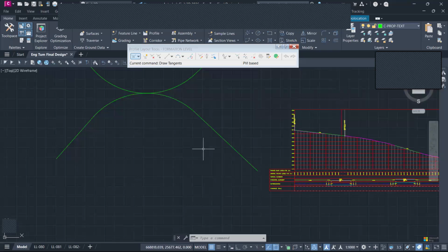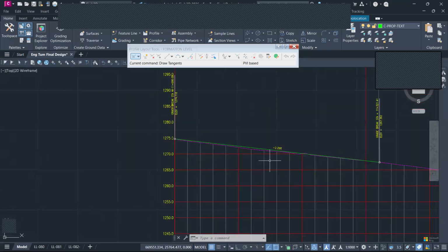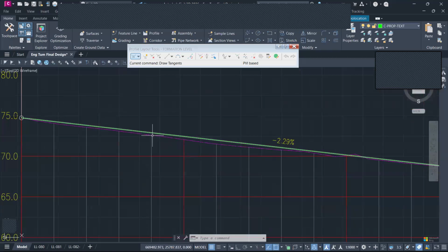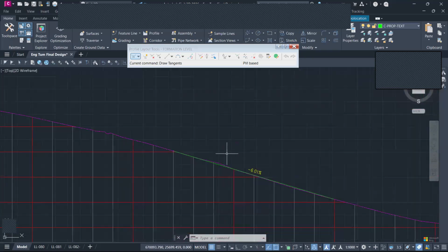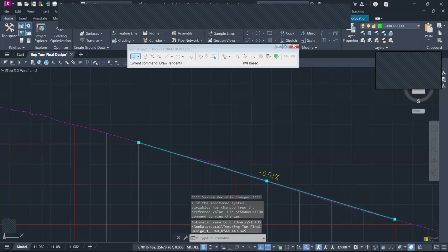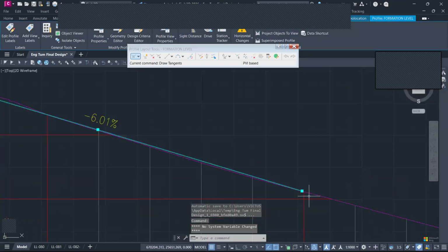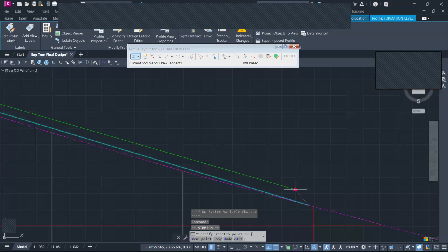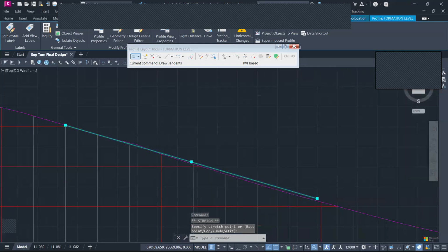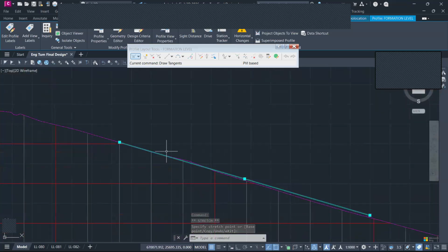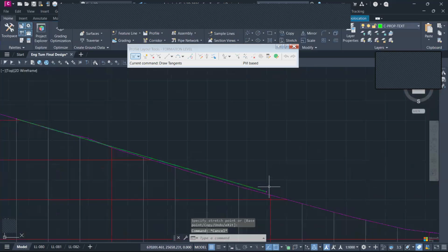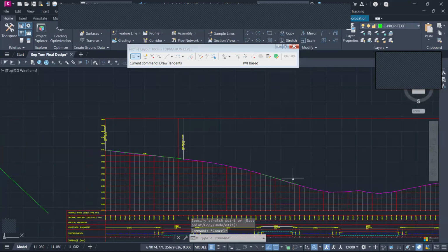Now, remember, as we noted when we were developing the design criteria, for a rolling terrain our maximum gradient was supposed to be 6%. So I'll check that this is within the range. When I look at this other point, it is coming to 6.0%, so I don't want to operate at that. I can level my ground a little bit on that side. Let me raise it a little bit at that point so that we see the final gradients that I will achieve.